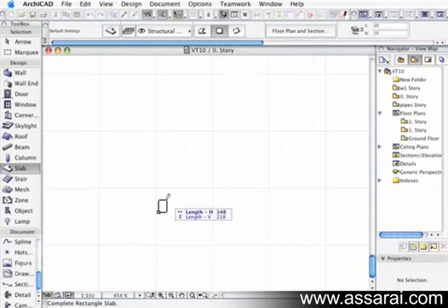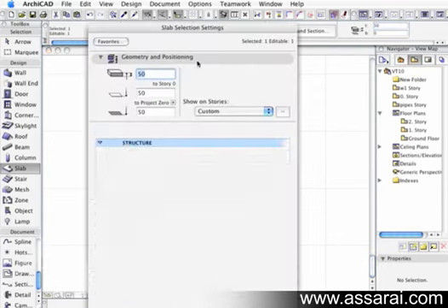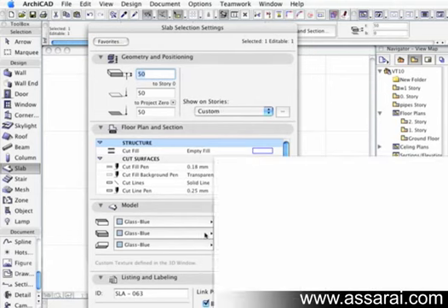moving H can be 820, and if I go down an arrow to the V length, that can be 2040. So there's my door leaf. Just going to make sure that I put that at 0 and the top of it can be at 50, so it's 50 millimeters thick, and make sure the material is black.